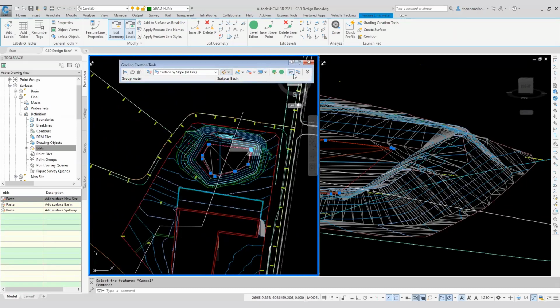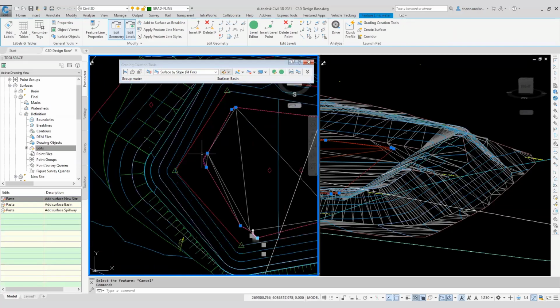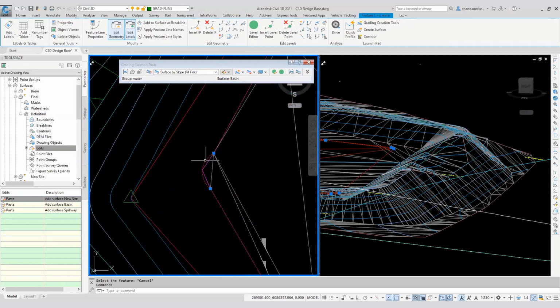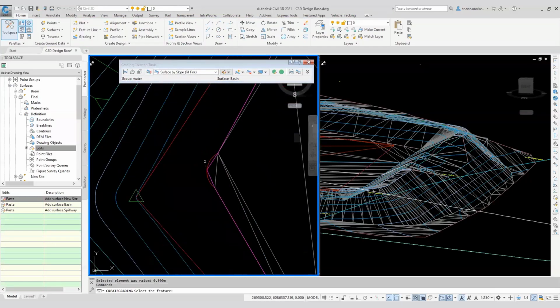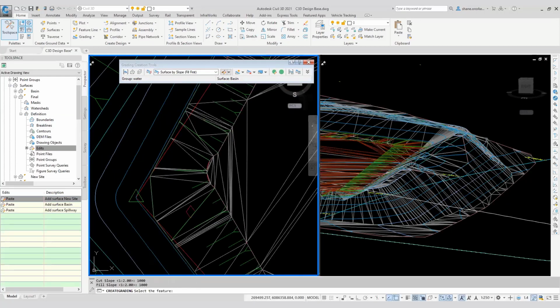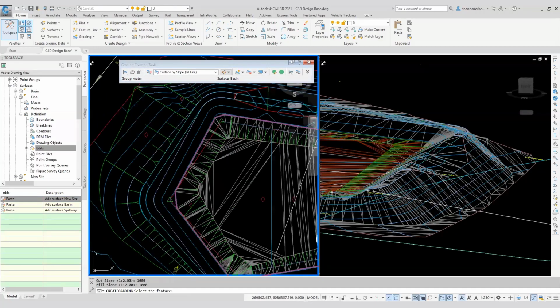So what I would do is probably review the geometry a little bit, get rid of this curve, raise it a little bit. I might just raise it by 0.5 meter, and then I'll try this grading again. So look, sorry, nothing 100% definitive on the best way to fix all issues. It really does depend on what's actually happening to what you try, but normally weeding the feature is the answer.